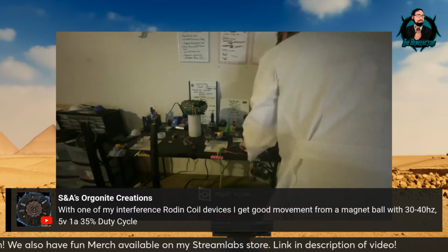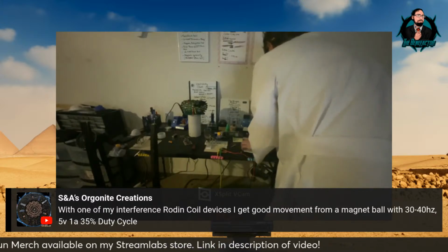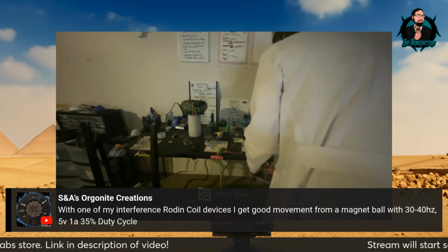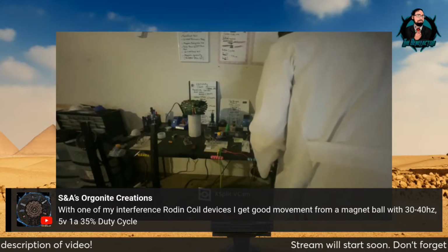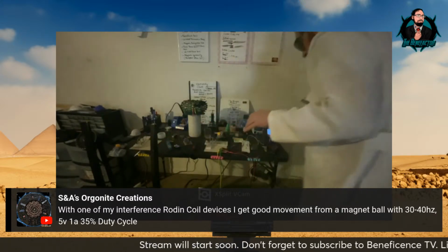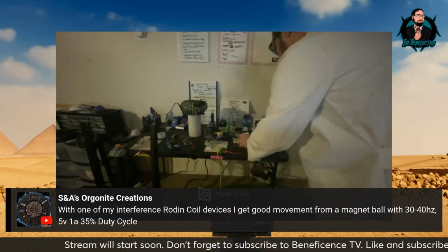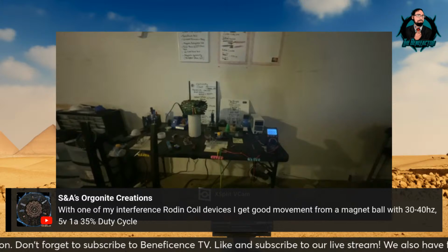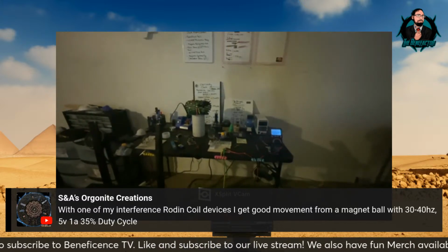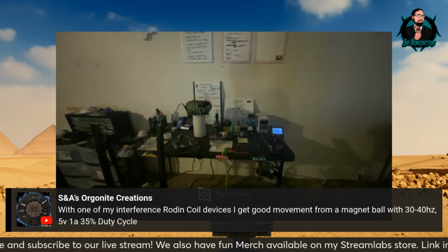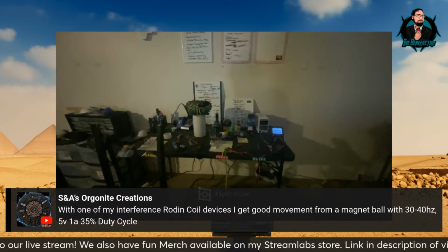Yeah, that DC is definitely a different animal than the AC going through there, Mike. I agree with you. So here's the thing. He's using about 5 volts. If you put 5 volts across an 8 ohm coil, it's going to draw 625 milliamps, a little over half an amp, which sounds to me like twice the amperage that the Bedini motor requires to run.